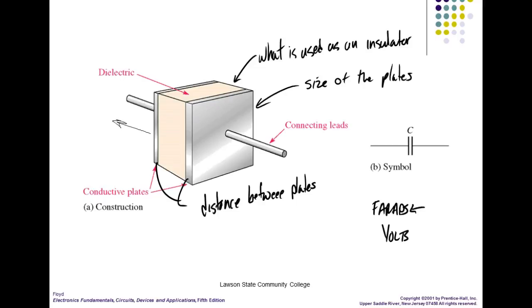Because it's got a dielectric, and to get these capacitors up to these sizes, that dielectric is extremely thin. And what that means is that if you get too high a voltage, it's going to punch a hole through your dielectric, and then your capacitor is going to conduct current through it. So is that the basics? Everybody okay on the basics of a capacitor? Really neat. I don't know who figured that out.